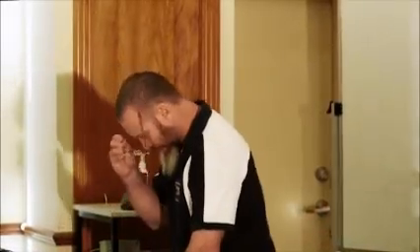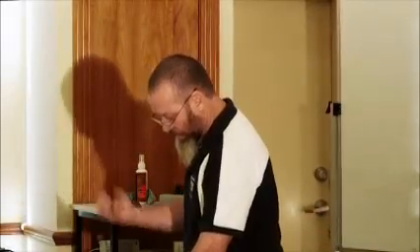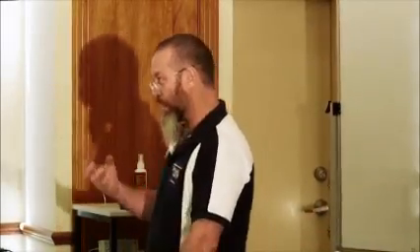And then, once you've selected the connection, you go back and just check that with your bracing. Now, I'll just apply this bit of common sense to you. Here's my bracing panel, okay? Now, it doesn't matter what the resistance of this bracing panel is, but if it's not tied down, it can do one of two things. It can do this one, okay? Sliding. Or it can do this. This is called a moment of rotation.